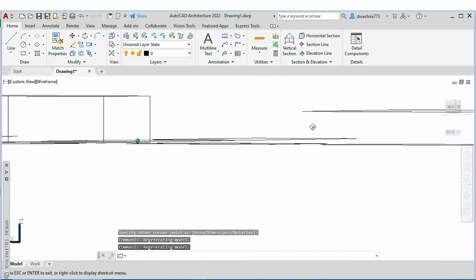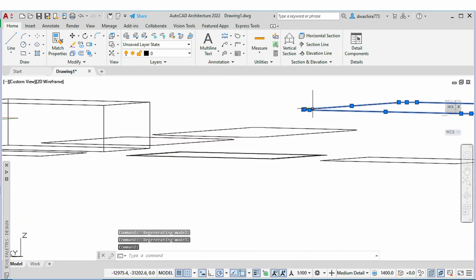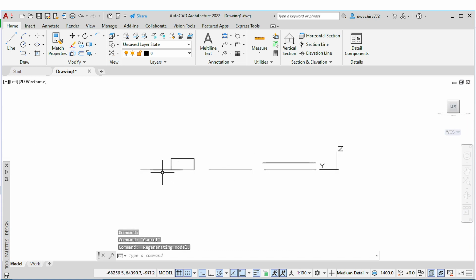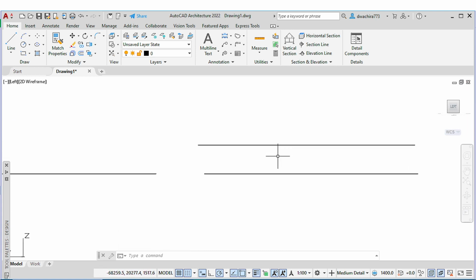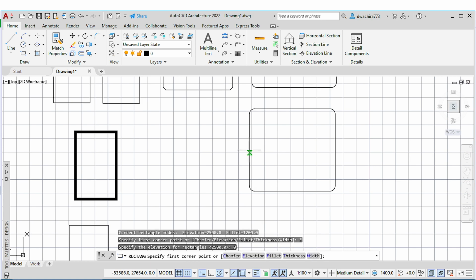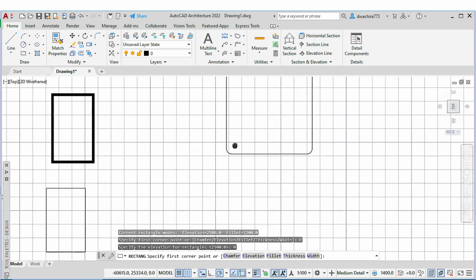Now you should note that this particular rectangle here is actually at a higher point compared to others that are on that particular plane. And we can try to look at this particular side view. So there it is, and the others are actually lying on this plane. So this is the elevation distance that you define when you are adding this particular rectangle. The elevation, you define it from this point. Probably I want it to be 0. Proceed and press enter.